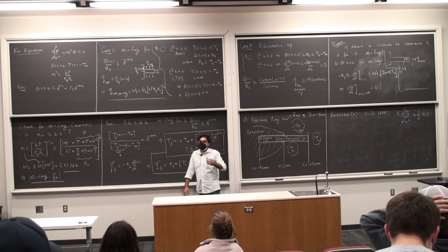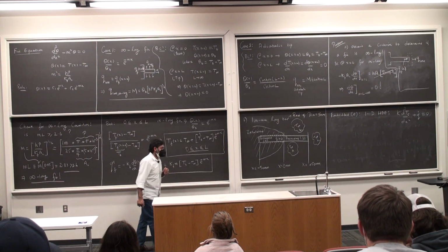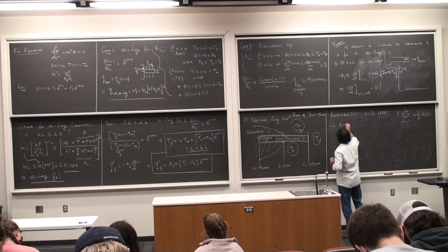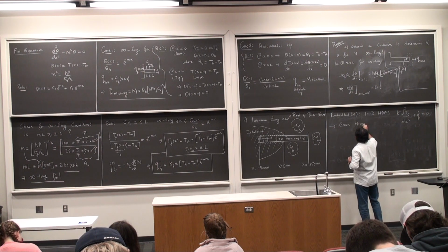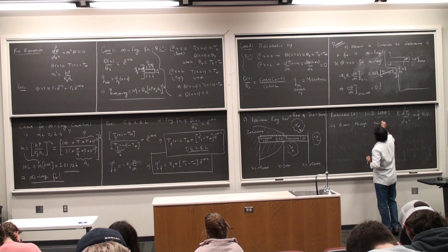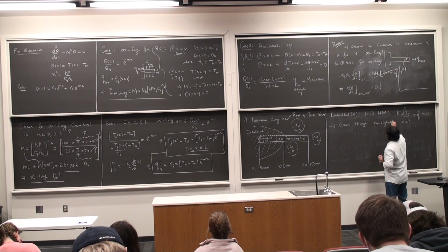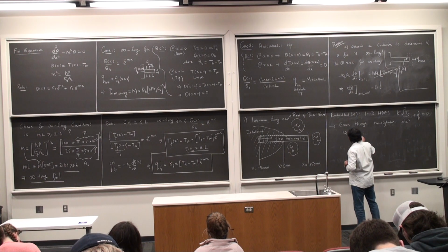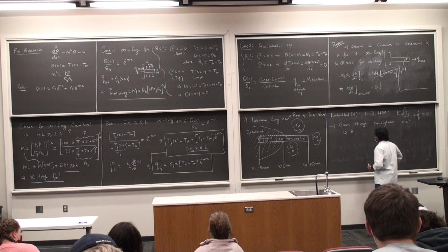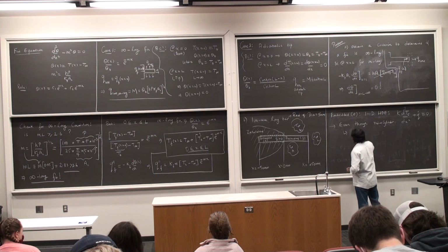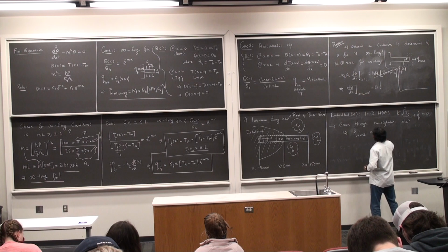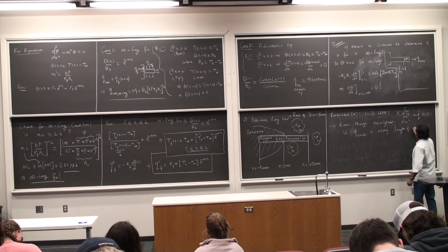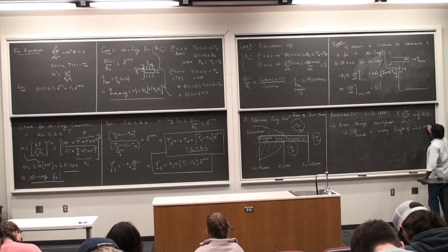So that's why you can't use the cylindrical. That's a good question. Let me clarify that here. So we cannot use it, so even though the rod is a cylinder, the conduction is along the length of the rod and not radial.